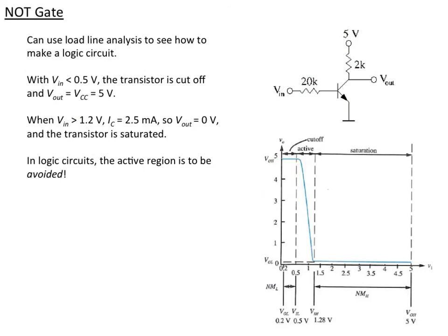And so you can see that here, this is how TTL often works. You have a low region for V out. It goes up to 0.4 or something like that, where you count it as 0, but it has a large region for high, because this just has to be above 1.2 to be counted as high on the input.